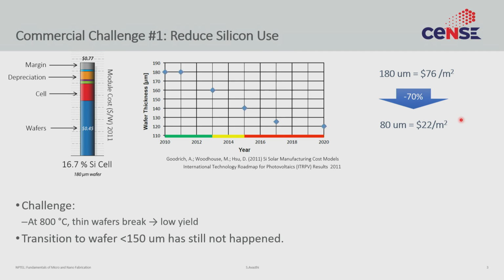But that was not an option for solar. So the solar industry really tried to reduce the amount of silicon, and the only way they could do that was by reducing the thickness. So they came up to this magic number of around 180 microns. This was for a 6-inch cell, which is still significantly thinner than what Intel is using. But any thinner, and they realized that they just break too many wafers. And because the yield is not there, they couldn't go any further. So the moral of the story is cost is one thing, but yield is extremely important. If you are not getting the yield from your process, you have to really rethink, because loss of a wafer is far worse than a slightly more expensive process.